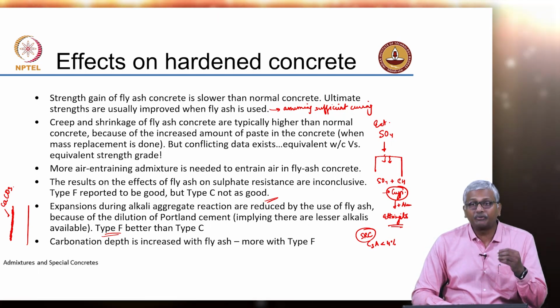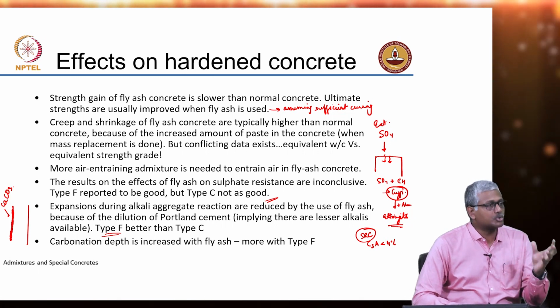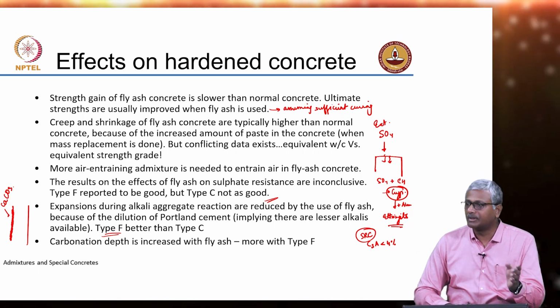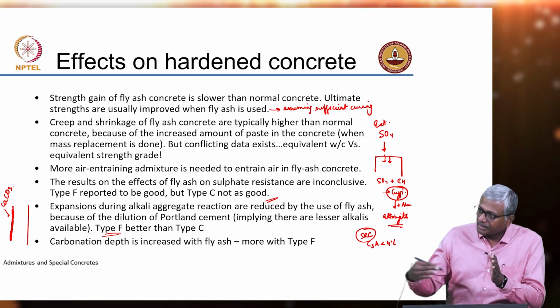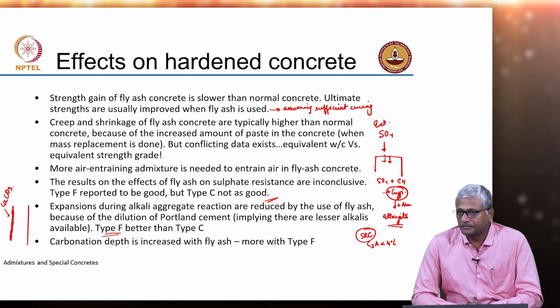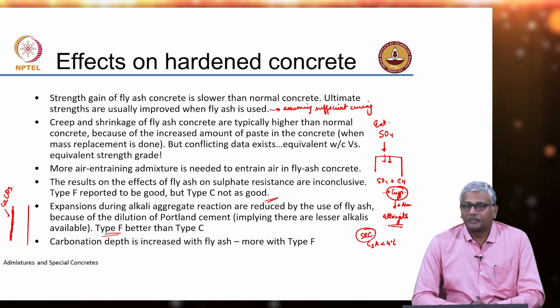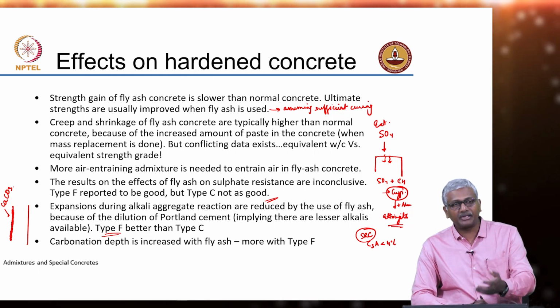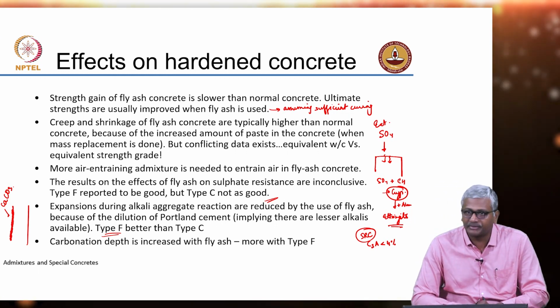Okay. So, you have to really look for that evidence in actual corrosion experiments rather than just basing your material selection on the rate of penetration of CO2. But for that to happen, one needs to do more testing, gain more confidence and so on.